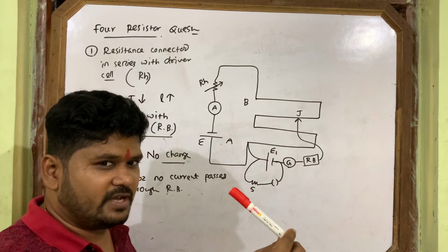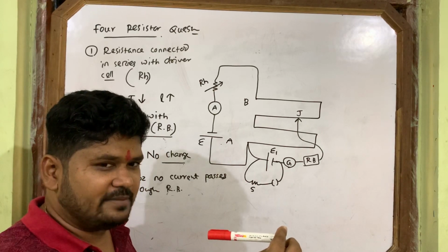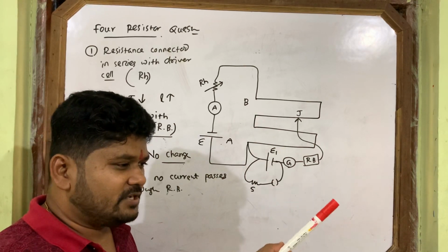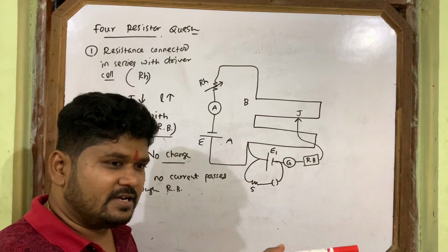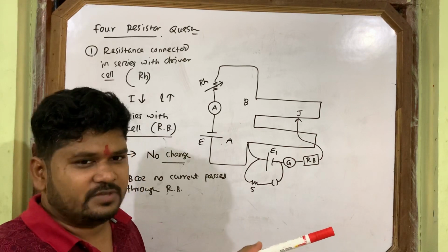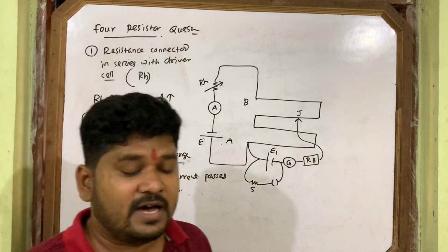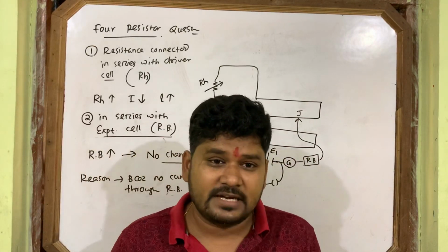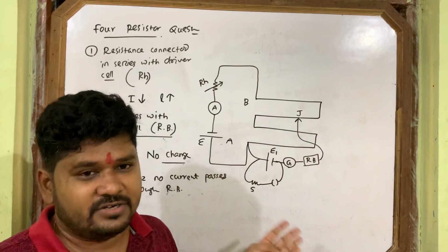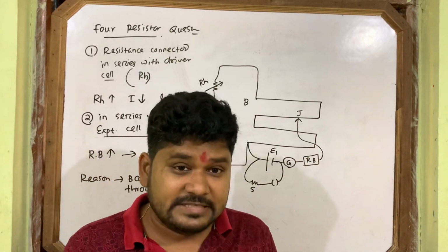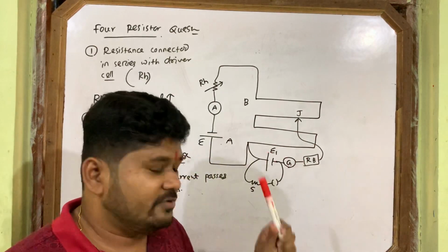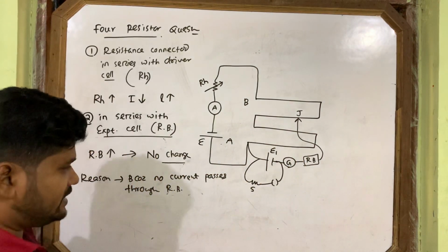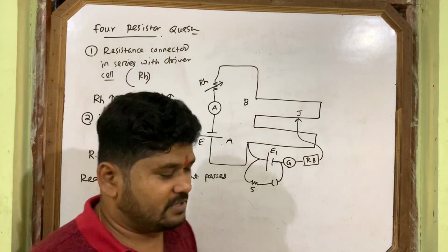Smoothly the pointer goes and, without touching the end, remains close to the end. And when you touch at B, again the pointer goes smoothly and stops very close to the end without touching it. Means no harm will happen to your galvanometer. So you just take 2000 ohm. That varies according to your instrument, your cell, your experiment. You see how much resistance to give accordingly. So now you understand what its role is. It is only connected to protect the galvanometer.